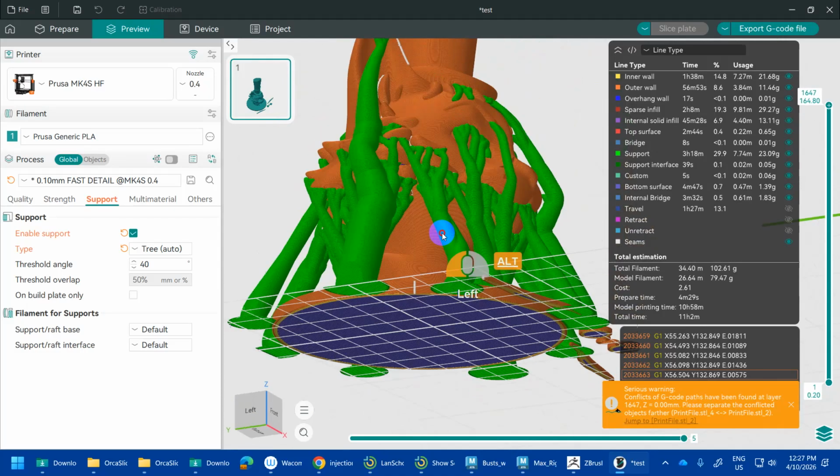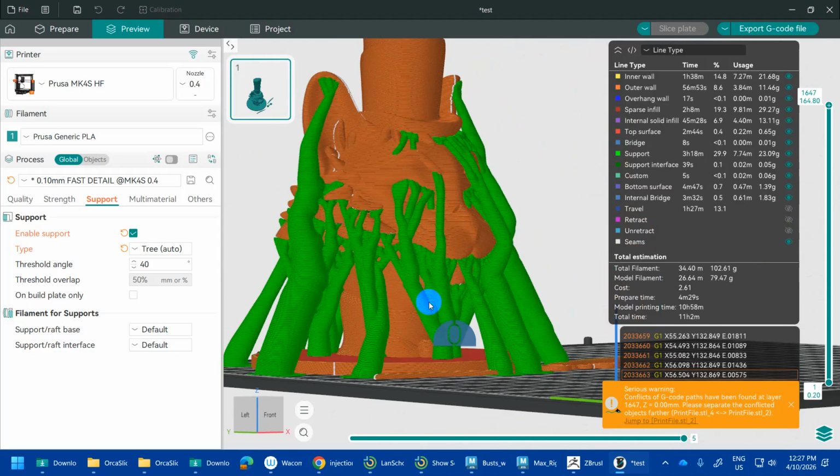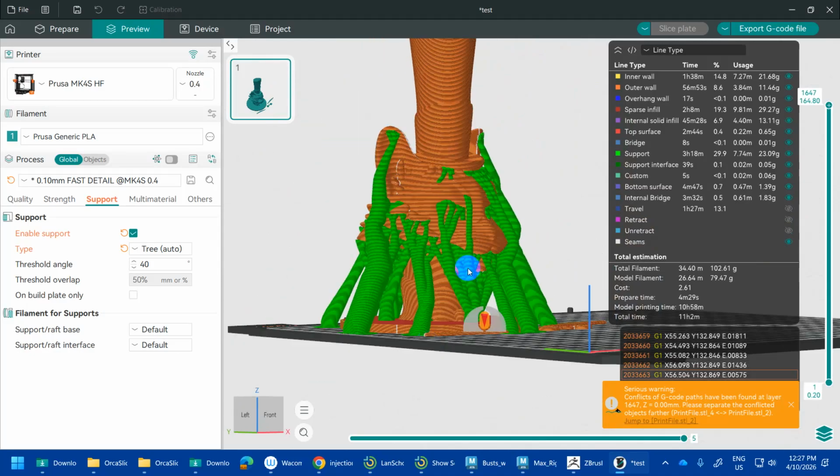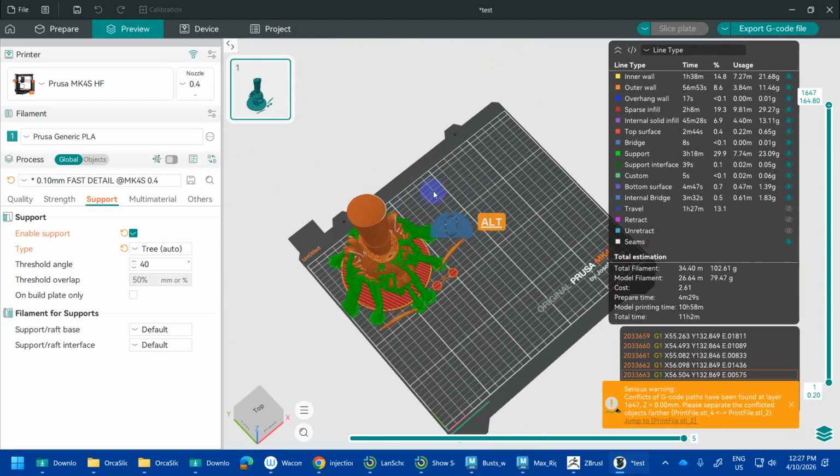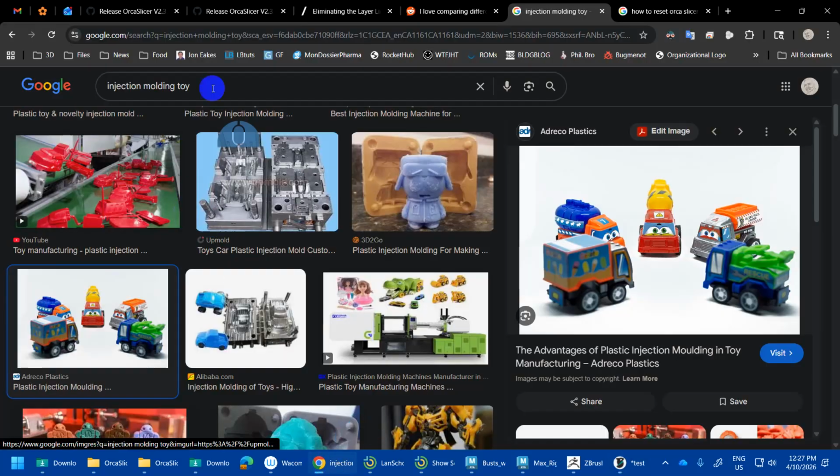Because the other thing is the plastic, while it's hot, it has to stick to the build plate. The build plate, which is this gray thing you're seeing, is literally a recreation of the actual build plate on the printer. It also heats up during print time. So once the print's done, it'll cool, and then it should pop right off the plate. But if your print doesn't stick to the plate, then you get spaghetti messes.